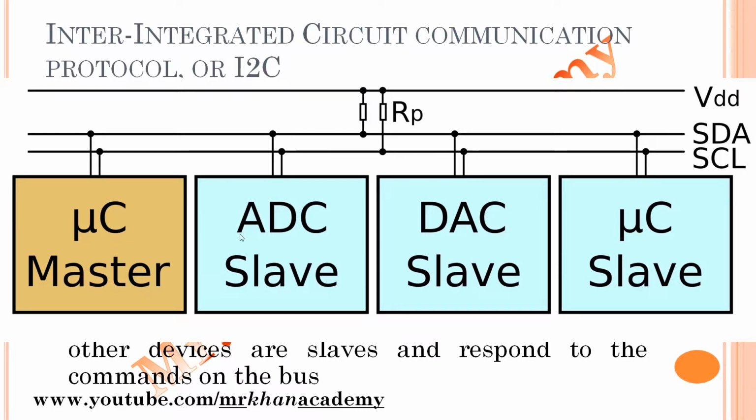Now the master is connected to all the slaves, might be sensor, might be actuator, whatever, with the help of these 2 wires. Those 2 wires are nothing but SDA and SCL. You can see each and every slave has the 2 pins, SDA and SCL. If those pins are available, then that device works on the I2C protocol. Then the common SCL pins are connected and the common SDA pins are connected.